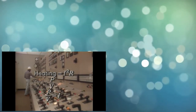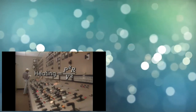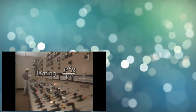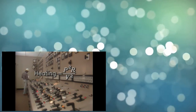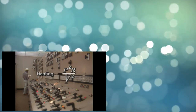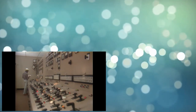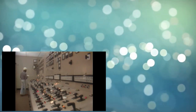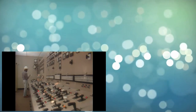Since I is P over V, that heating is P squared R over V squared. So for any given power and resistance, the higher the voltage, the less power lost in transit. In other words, the key to transmitting power efficiently is to transmit it at the highest possible voltage.